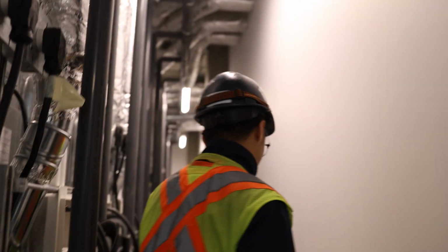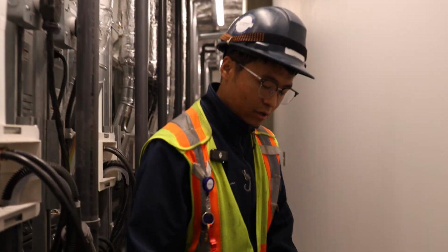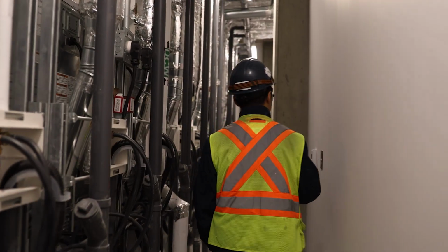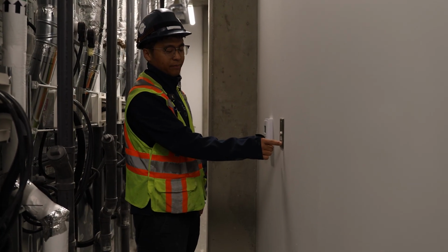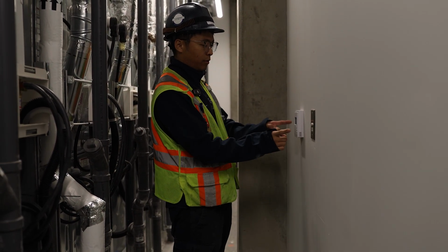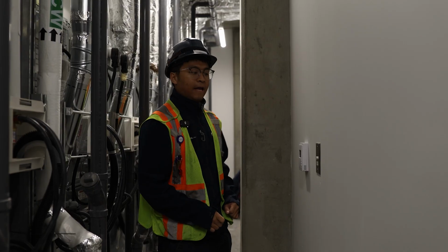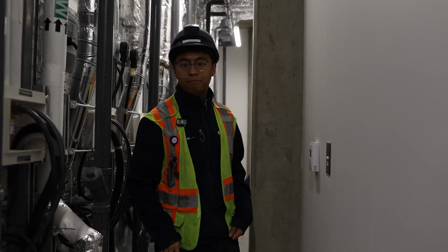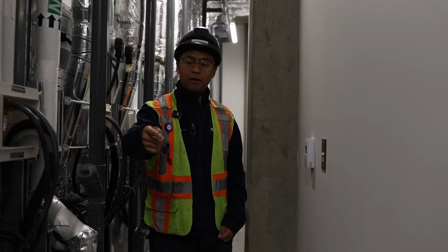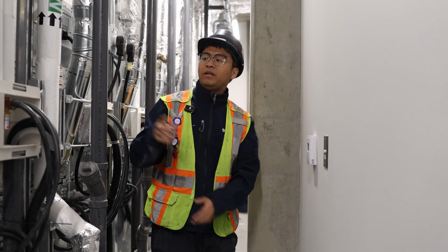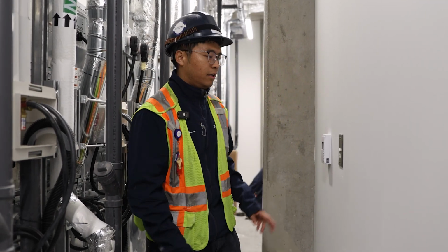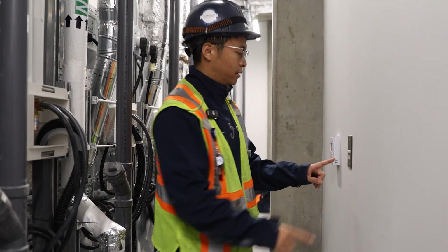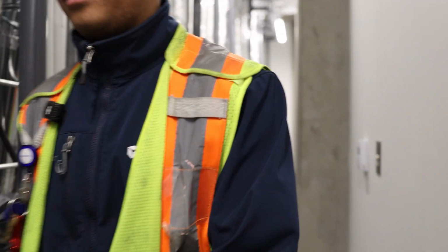This will be the discharge. The air will be coming from the makeup air unit, and then the BMS monitors the space pressure and also the space temperature. This pressure has to be around 0 Pascal for the makeup air unit to make up the air being exhausted by the dryer. That's for the Planium number 1. I will show you Planium number 2.